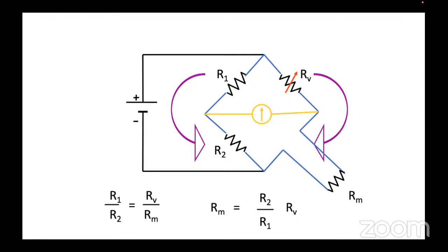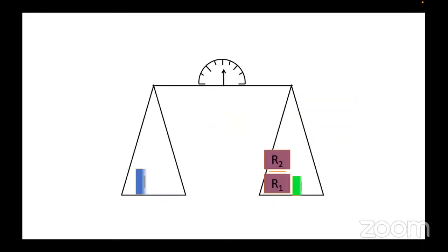So if you already know R1 and R2, we can then balance the bridge across, because if the resistance changes, it is measuring the resistance, then you can actually change the resistance of RV, so balance out to bring it back to 0. So the amount of the current applied to bring it back to 0, that is the change in the voltage here.